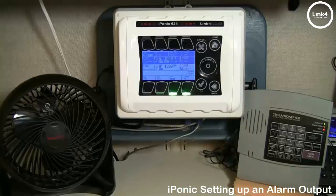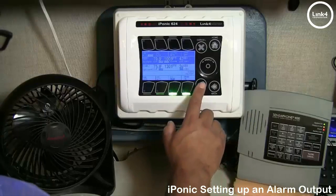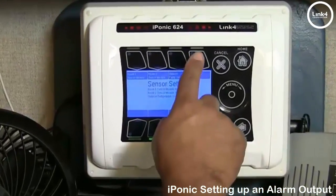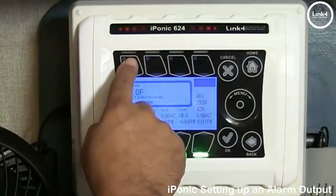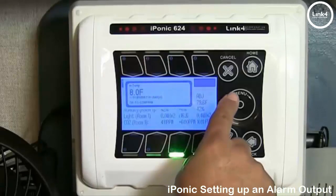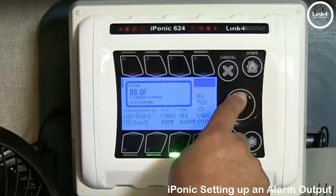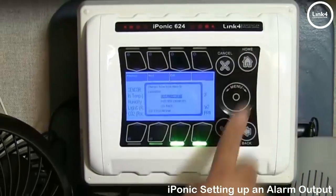And we'll simply simulate a high temp alarm scenario. And we'll do this by increasing the actual temp reading on the controller to be about 150 degrees. And to do this, we'll hit OK, System Setup, and we'll go to Sensor Setup, Advanced Settings, Manual Calibration, Edit the Cal, and we'll make it roughly about 150 degrees. Hit Home and Save.